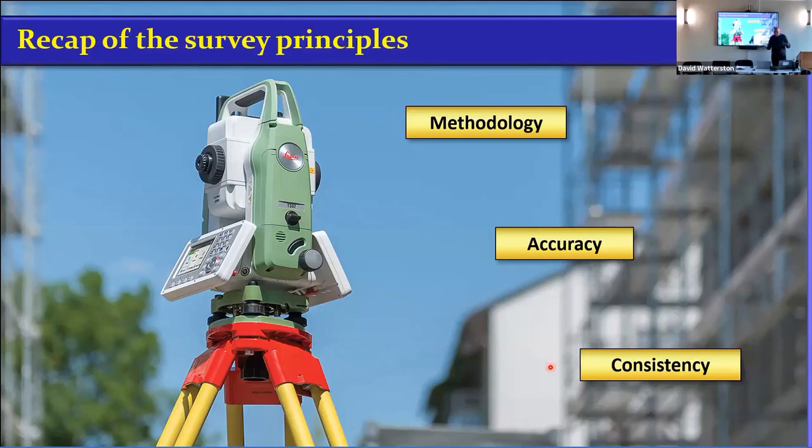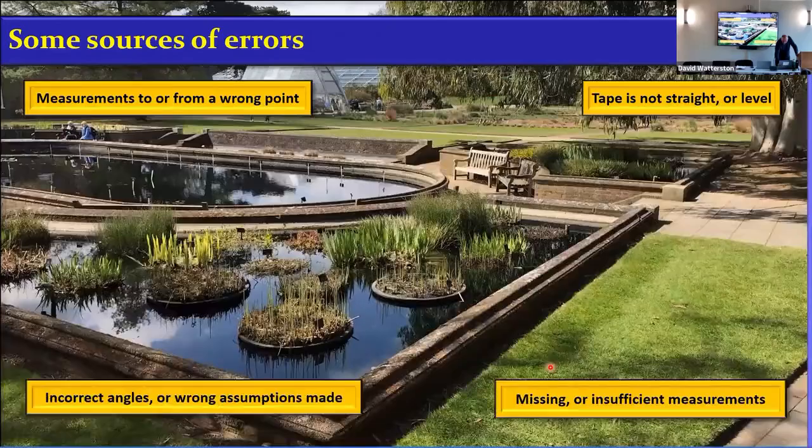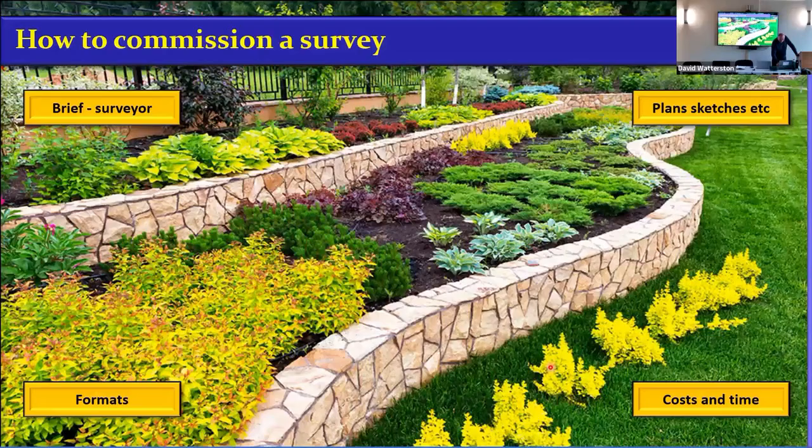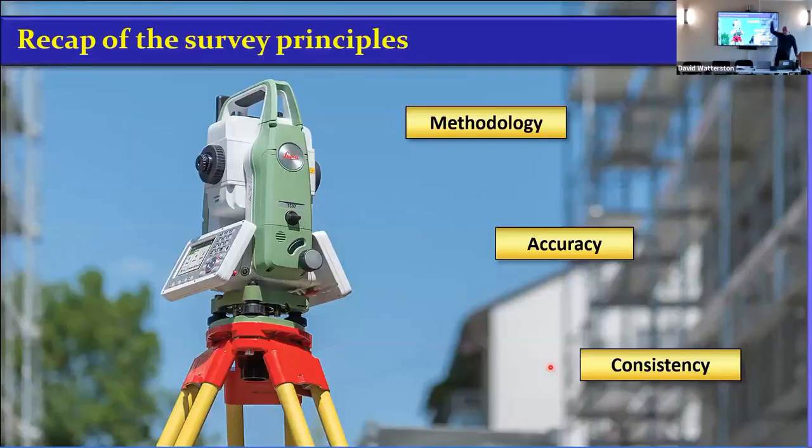So when I said to him, can I have some control put in so that I can control the job, expecting him to put a little peg in like this, right? He put me in metre cubes of concrete with a steel bar all the way through, 3 metres down. So they were not going to go anywhere. And even if there was swell with the clay and things like that, they were there forever. So I said, that's wonderful. So I was centre punching these and then measuring between them.